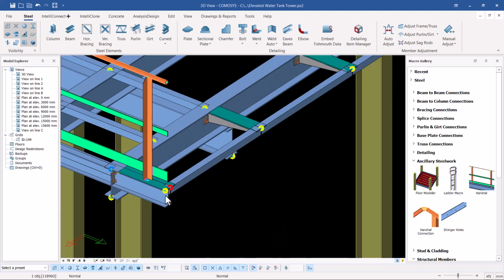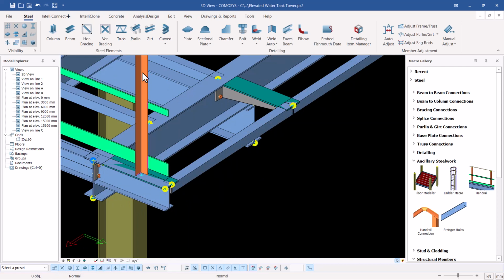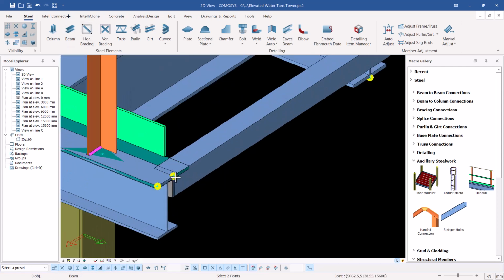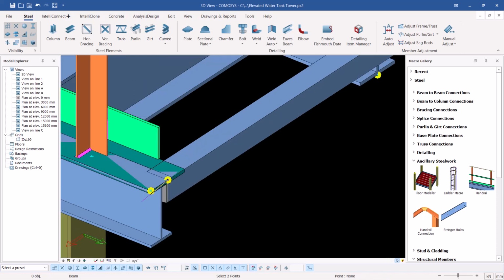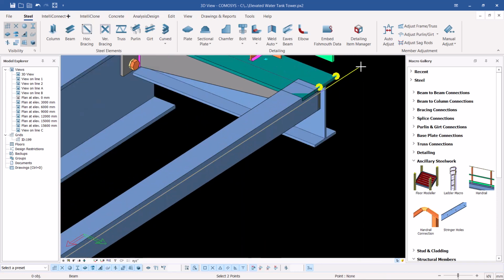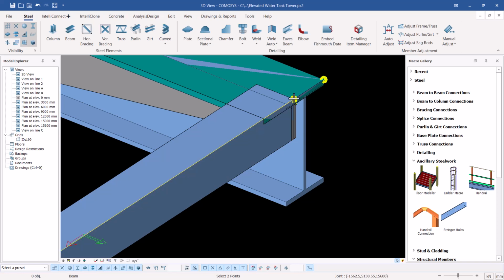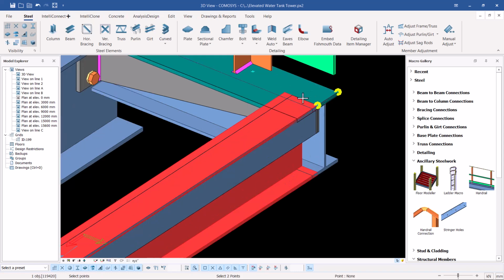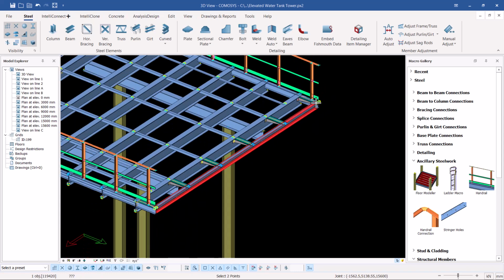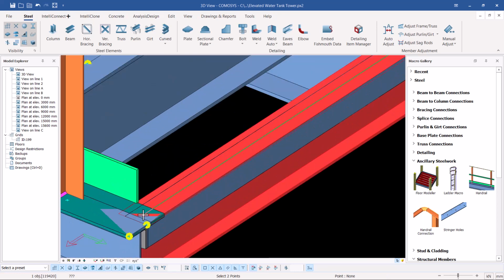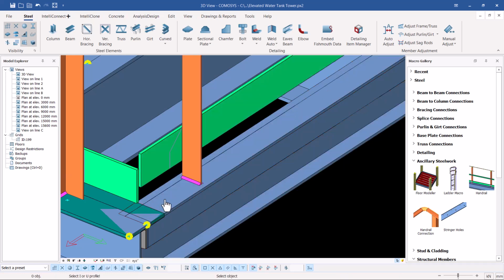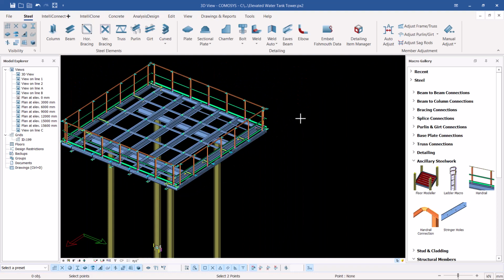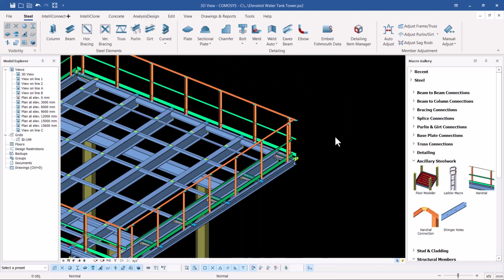If you look on this far end, we don't have the beam we've created here. I'll come to beam and snap right here, and move all the way to this far end here. That's the location we intend to place. Let me select on that, right click, snap on that spot, zoom out and come all the way to this far end here, and snap right there. So we have our handrails in full and in the accurate positions.